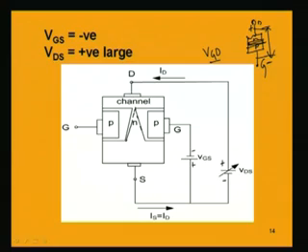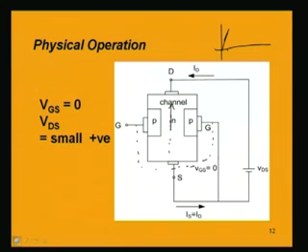Because of these phenomena happening in this JFET, for variation in VGS as well as variation in VDS, keeping one constant at a time, we can now draw the VI characteristic. Now, one thing to note is that when VGS was 0, the current which was flowing between drain and source, due to the presence of the small positive voltage VDS, that saturating value of that current is known as IDSS.